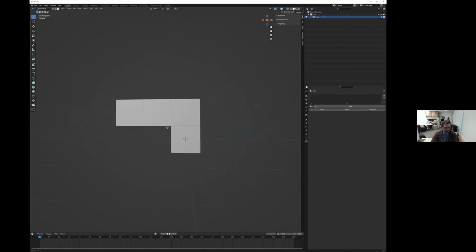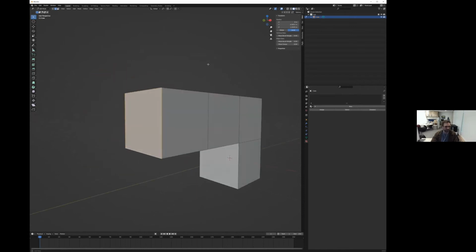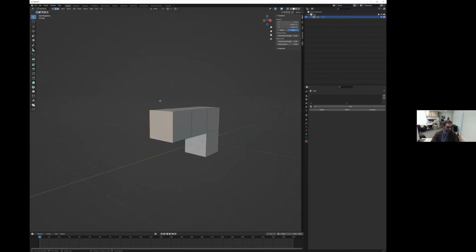I guess, L. And if you wanted to fill it, you can go to edge mode, and you can select all of these, right? The bounding box. And how do I fill it? Fill starts with an F. All right, so that worked, great. So easy enough. If you didn't want to select all of them, you could press Alt and then click the edge loop. This is called an edge loop because it's looping around the model. And then you can press F.